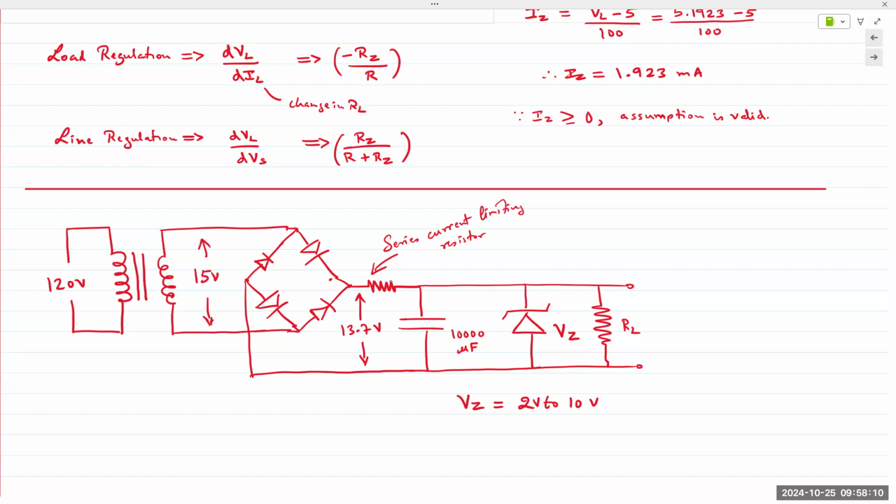Going on a bit of a tangent, in real life, there are actual voltage regulators that we can buy, 7800 series, 7900 series, and they come in all voltage ranges. Okay, so each voltage regulator or each Zener diode that we buy will have an input range on the manufacturer's spec sheet that describes the range that we can actually use the Zener diodes. Okay, and so this is the experiment for lab next week, and that's where you'll actually look at the spec sheet and become familiar with many of the terms. Okay.